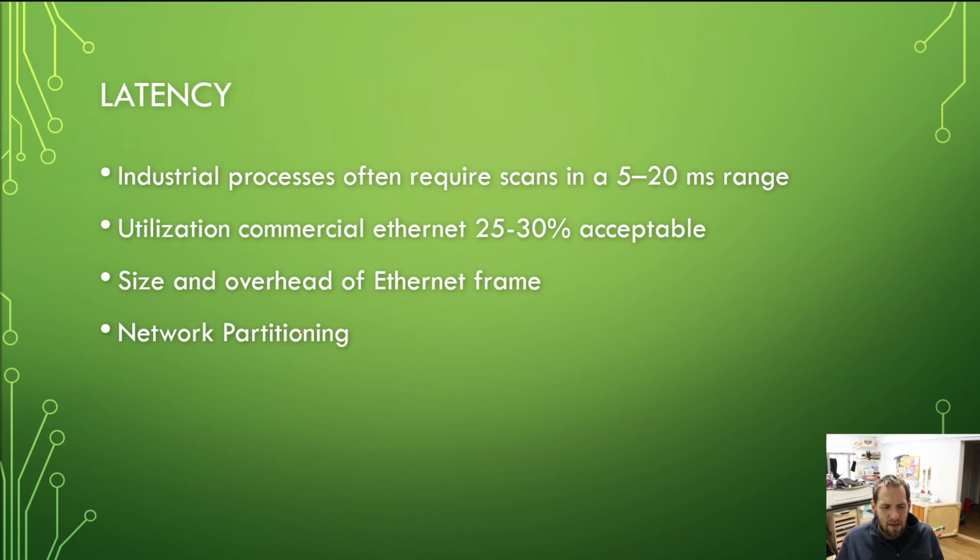Some PLCs or some network industrial equipment will do what's called exception reporting. All right. So when my PLC is looking for information about whatever I/O or our remote, they're too far away to run normal cables. We run an Ethernet with another device there. They'll do exception reporting, which is they only report things that have changed. All right, and that helps keep our network traffic down.